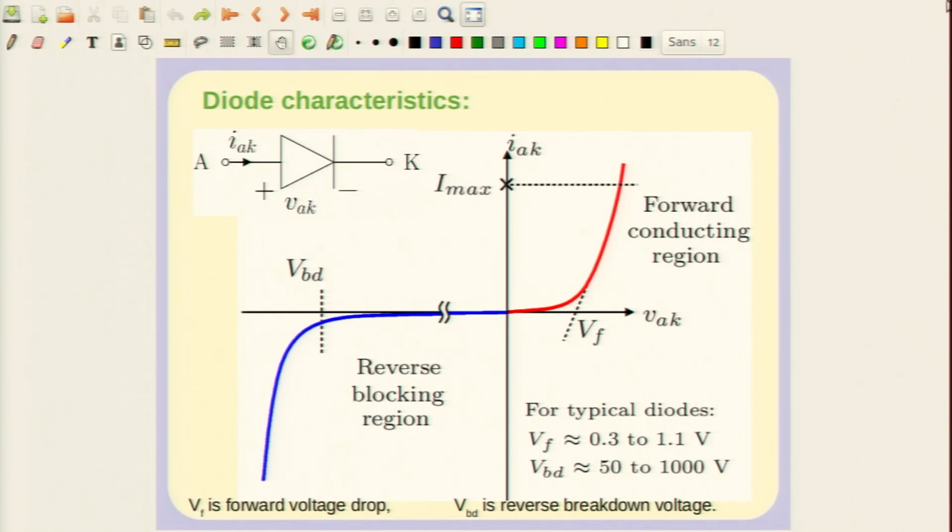Now, power conditioning circuits we began last time by considering a simple diode and its characteristic. So, we will quickly go through it and look at some of the important circuits. Okay. Now, we saw last time that this is the characteristic of a diode, and the reverse breakdown voltage VBD is quite high, and Vf on the other hand is small, and the slope of this curve in the forward direction is extremely high. So, it has a very large conductance. Remember that we are having an IV characteristic, I on the y axis and V on the horizontal axis.